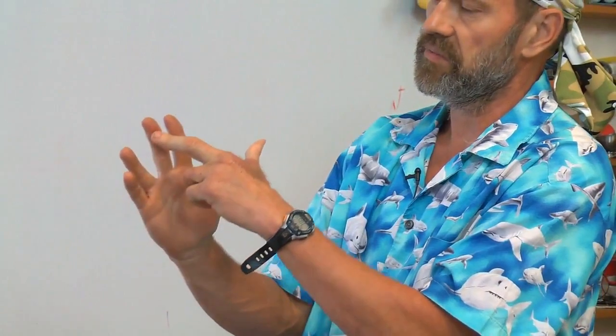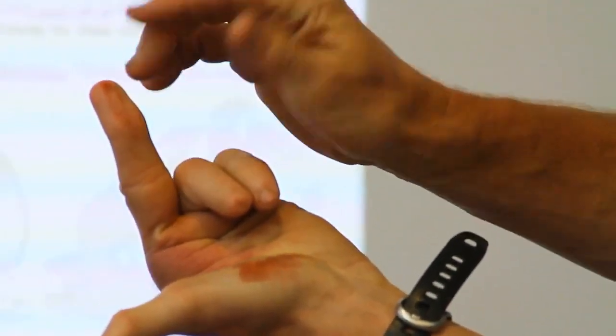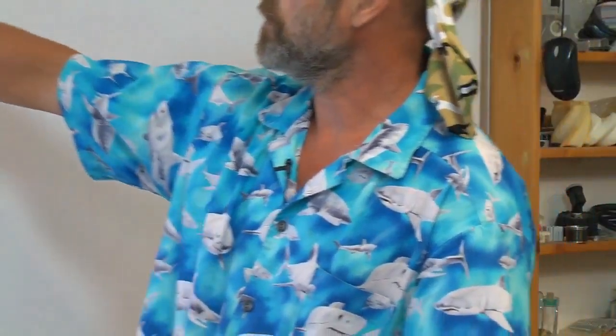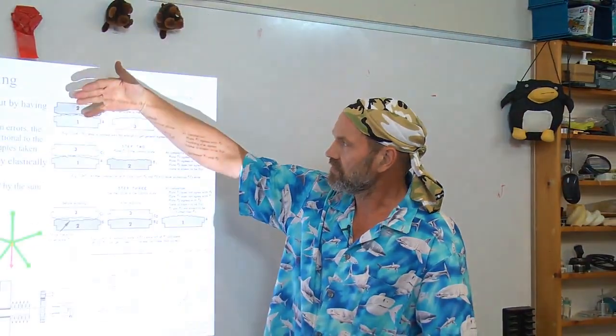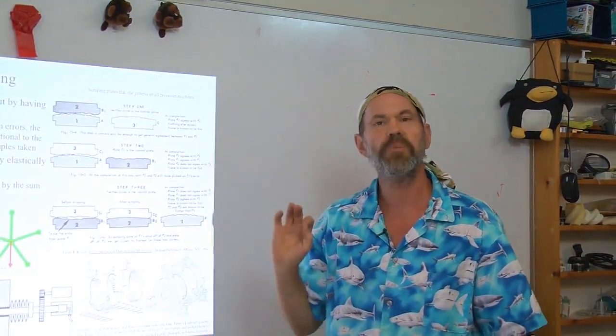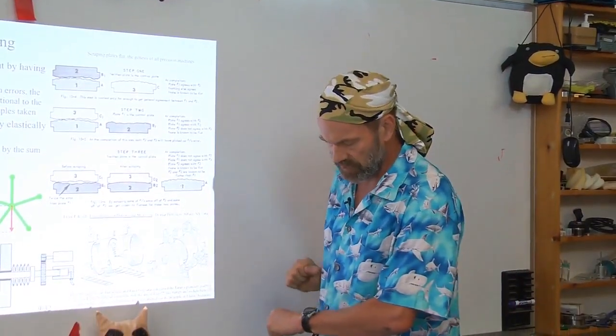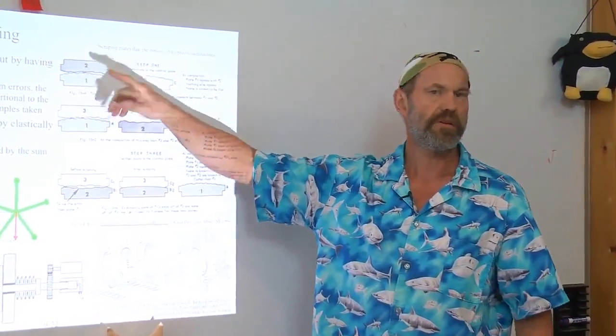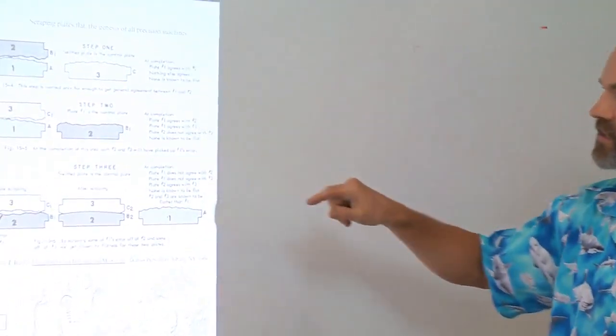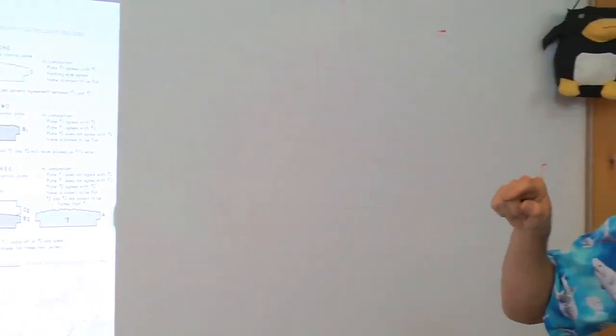can't see it too well, but you see a little bit of brown on the finger there. Comes from it, and you can see here where it's been transferred from here to here. You can take two surfaces, put some coloring on one, put it to the other surface, rub it, and you'll transfer some color from one surface to the other that will tell you where the high points are. And that was a tool then used, a scraper, looked like a razor blade, to then scrape off the high point and repeat the process. And with three plates, in a round robin scenario, you could take three huge plates even, and very slowly, carefully get them flat to within a few microns.